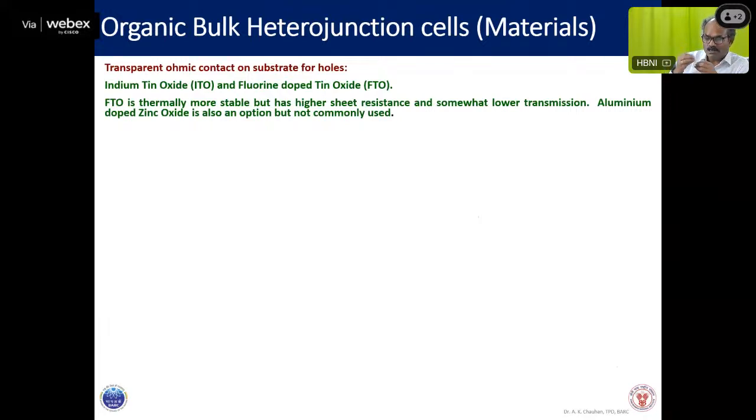They absorb every amount of radiation, because the energy levels of the electron are allowed in there. So they will absorb all radiation, and electron hole pairs will be generated in all the cases, but they will not be separated. Since they absorb radiation, they will not transmit it. Very simple. But there are certain materials, that is ITO, FTO, and zinc oxide based ones also, which are conducting but transparent, because conductivity in those materials is by a different process, and that is vacancy based. So vacancies are created.